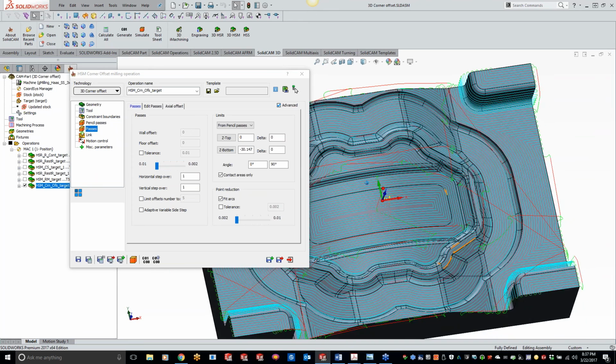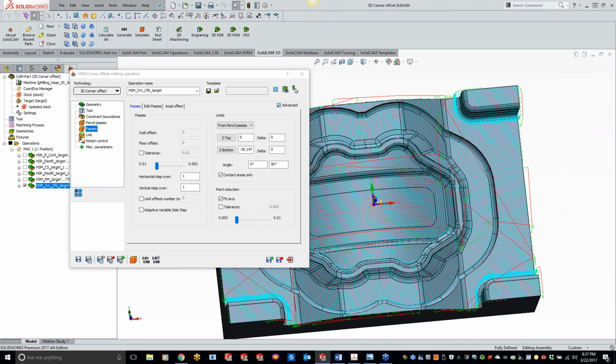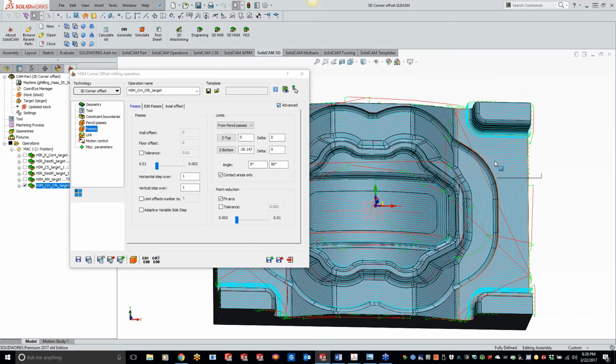Okay, so like I said, pretty basic. We're taking into factor that we're using a 3D constant step over, pencil milling, and the parallel pencil milling passes, and combining all three of those strategies into one. So any questions on this? We'll go on to another part here, but you guys will get real nice toolpath, nice finishes, everything there. And obviously each part, the toolpath will depend on each part and how everything looks for you guys.